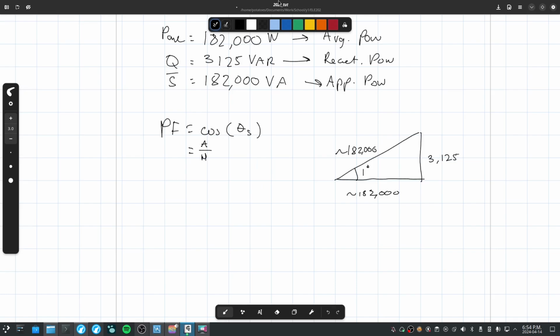They're both the same. And you'll get, in this case, at 1 degree, 0.99985. It's incredibly close to 1, which is also why I got literally the same answer, because I wasn't accurate enough. Now, this points upwards. You have a positive degree, so this means that it is lagging. So you write down that the power factor is 0.99985 lagging.